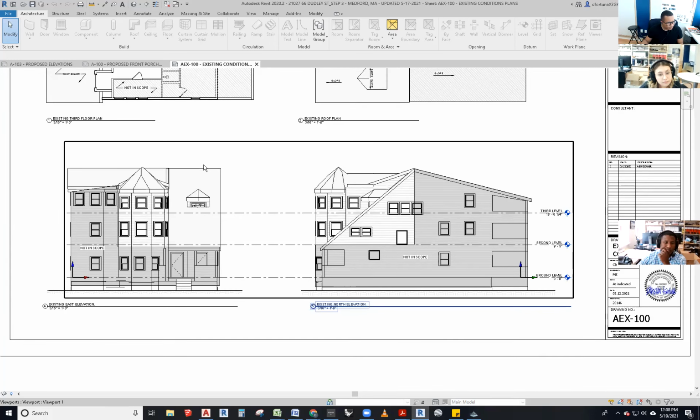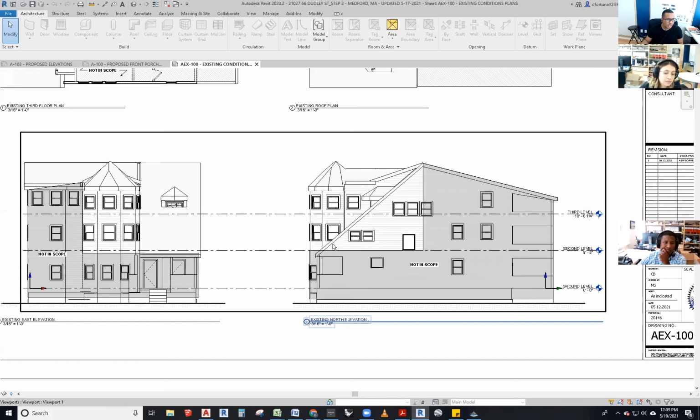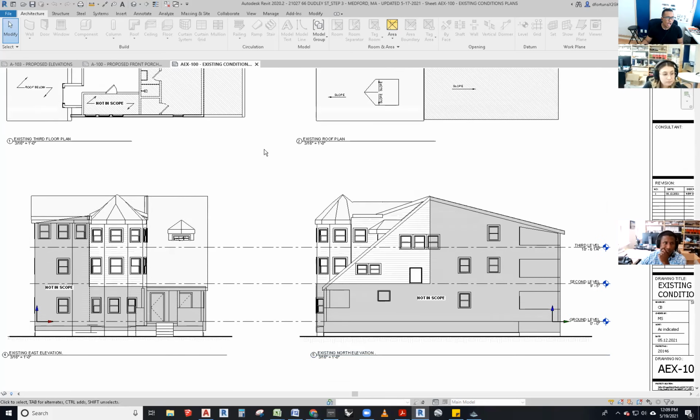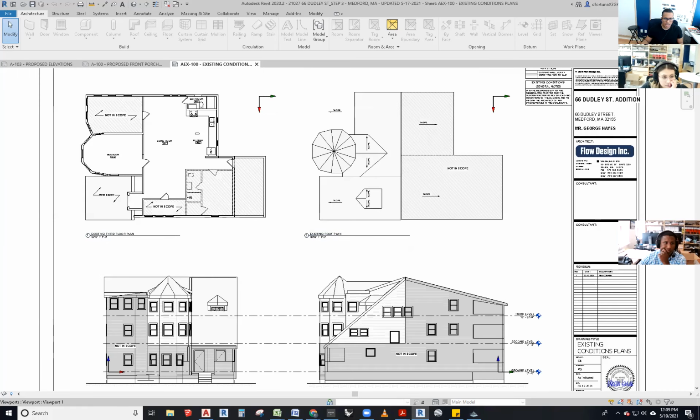Basically, the things that we need to think about when we're doing this are that we're going to need to do new roof rafters. We might need a new roof beam, a ridge beam. These pieces of floors that we have here now are going to have to extend, so we'll probably need to add another beam to join them, and new floor joists. And then how does that get transferred all the way down to the foundation? I'll try to make this as quick and efficient as possible, but that's the task at hand.